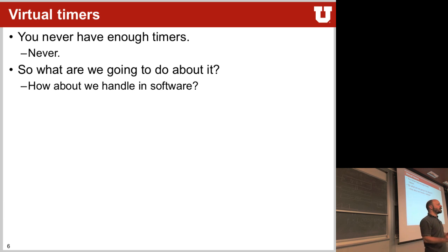You basically have to virtualize your timer, right? You somehow have to juggle and figure out, okay, event number 6 will be the event that comes last. So I first handle my first one, and once that's handled, I will write event number 6 into that particular compare register. That way you could do it. So you have to have some sort of a linked list that you keep in software, that has a list of which event happens at what particular time. And this list has to be somewhat ordered in software.